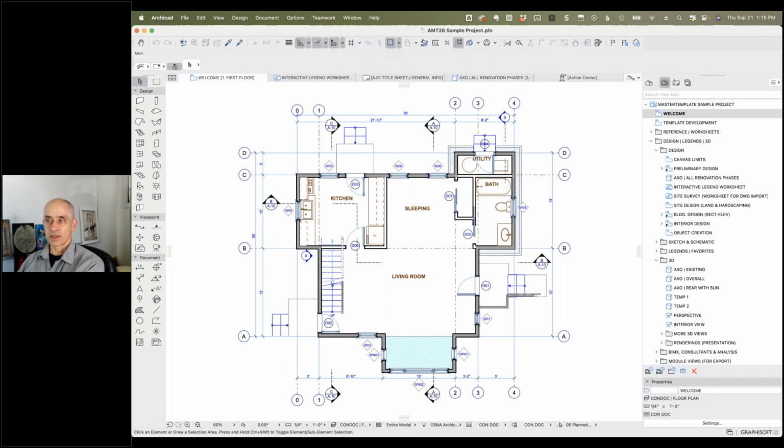And if the control points become awkward because it's really not a roof system, it's just sort of arbitrary points to meet your geometry, then you could use the mesh to roof tool to create a series of roofs from the grade points that you've got. And so then they do have uniform thickness because they are all roofs. So that would be another demonstration. I can certainly do that.